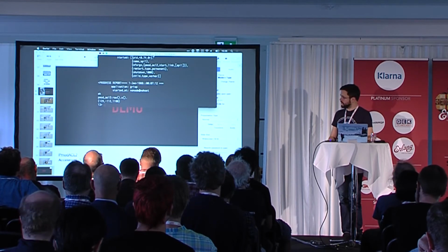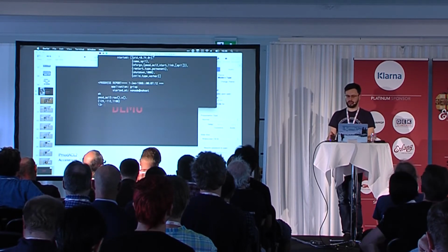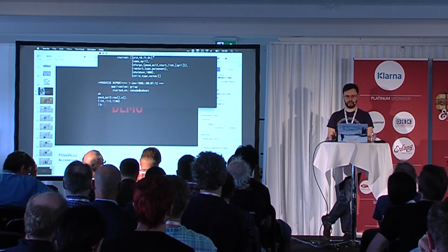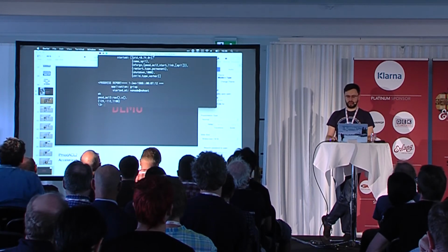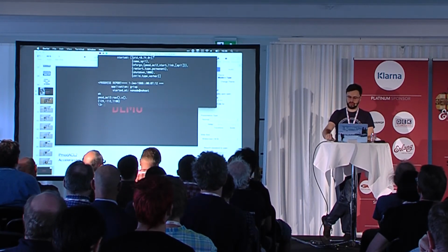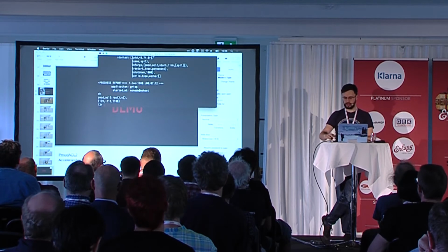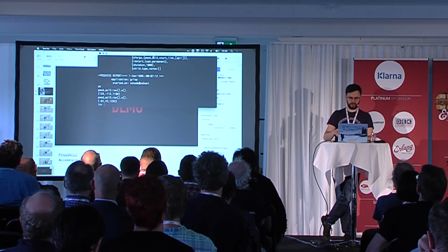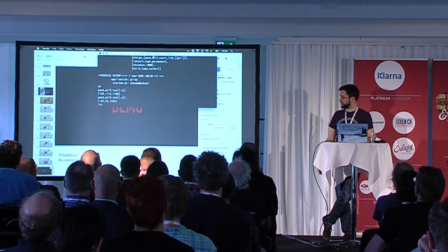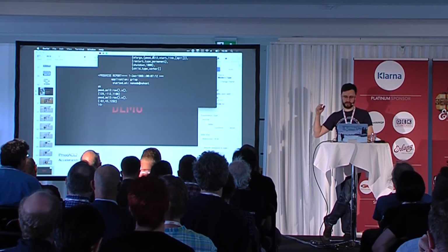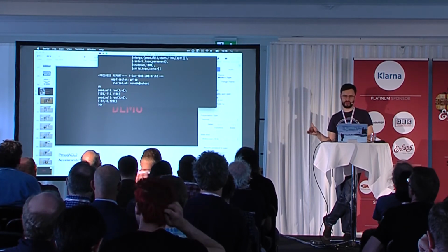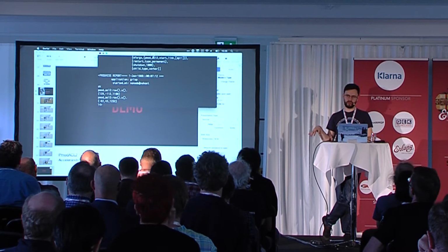So this is accelerometer data. This is the raw values that come out of the device, and you can convert them to g-forces. If I just lay it super flat like this, you can see that the third component, the z-axis, is about 1000 and the others are about 0 to 100.